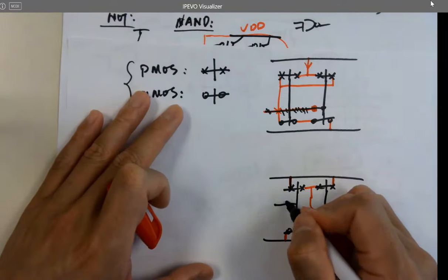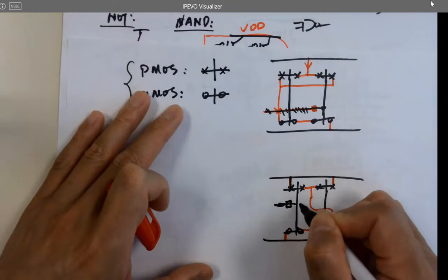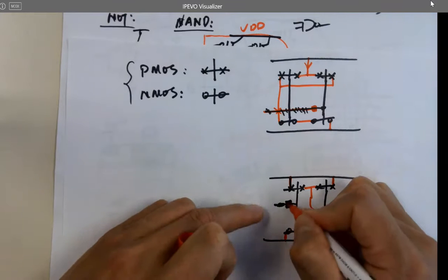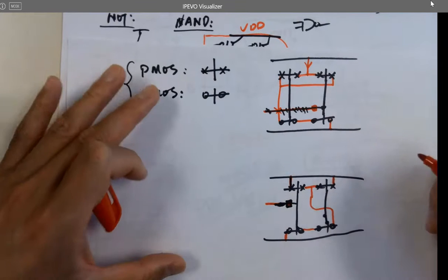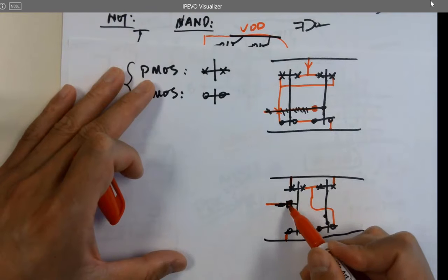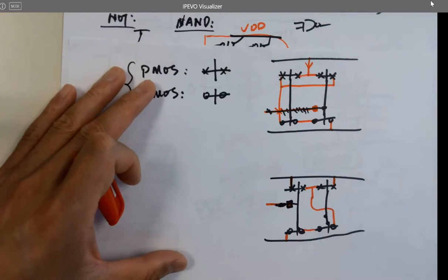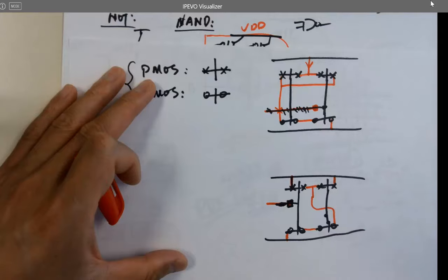So usually right after that, just beside the poly layer, you need a via to metal 1. You know what I mean? That's what you usually do. You'll see in the lab. So you introduce metal 1 just beside that poly, so you are not using a too long poly wire. You just use a metal 1, which will reduce the resistance.